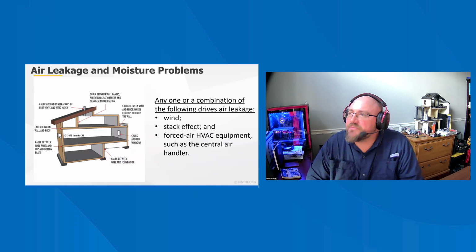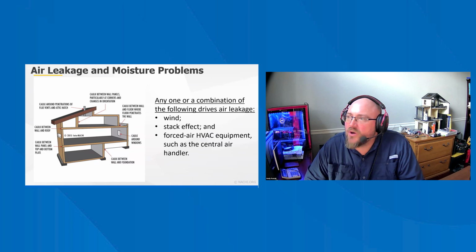Air leakage through building assemblies can move large quantities of water vapor and is a major factor in many vapor-related moisture problems. Building envelopes should be constructed to reduce air leakage from inside to outside in cold climates and from outside to inside in hot, humid climates. To achieve this objective, the big air leaks in the building's envelope must be sealed. Most insulation will not stop air leaks. In addition, a suitable air barrier system should be carefully considered and installed during the construction of the home.